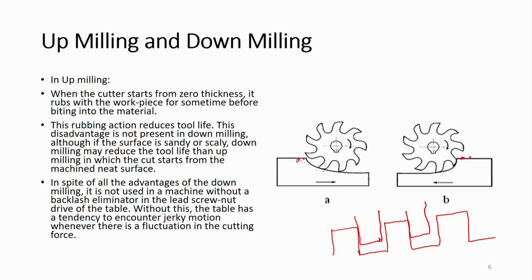Ideally, the thickness of this gap in the screw will be equal to the thickness of the teeth of the thread of the nut, but usually that cannot be done, because if you make it very precise, then it may jam and will not have free movement, and due to thermal expansion also we need some space. So, we deliberately provide some gap between them, called backlash. So, that is not a problem.